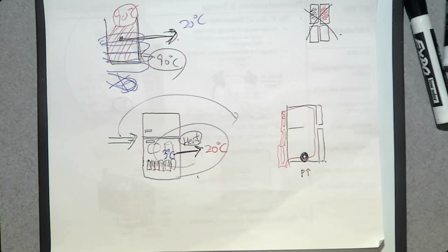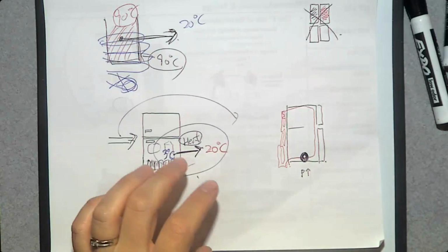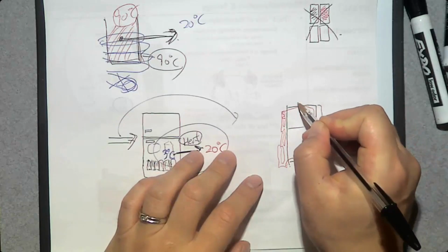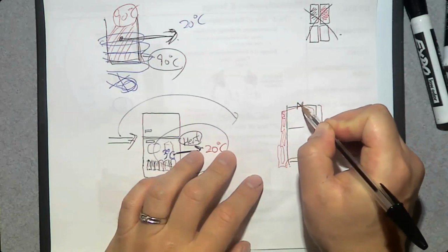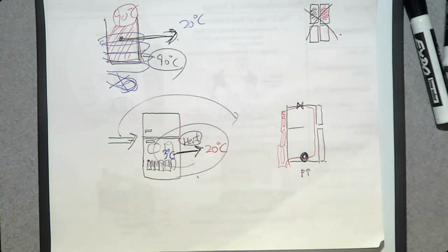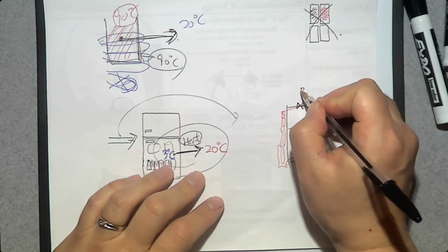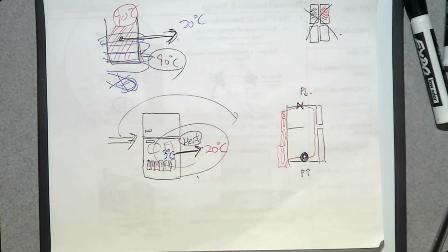Then, if it increases pressure and you keep running the system, the pressure is going to increase continuously, which doesn't make sense, right? If you increase pressure, you need to decrease pressure to maintain constant properties. So there's another device on top. It's called an expansion valve that drops pressure. So at one point, we increase pressure. At another point, we decrease pressure. Now, let's see what happens.